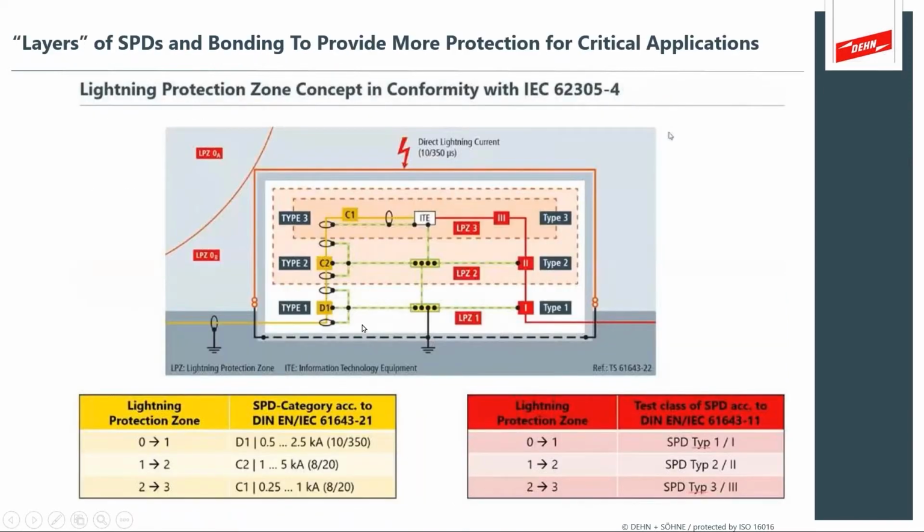So this all contributes to what we would call layers of protection, and to create a zone of maximum protection. So you have something like your most exposed point of your AC power distribution coming in. And then as it goes downstream into your electrical system, you can build more and more thorough zones of protection. And this is what we can look at at a block diagram level, and then you can inspect your site and see that it was actually implemented correctly.